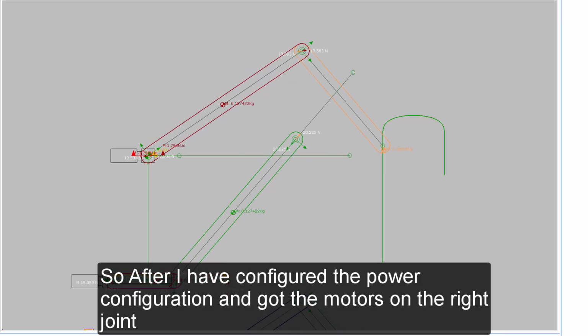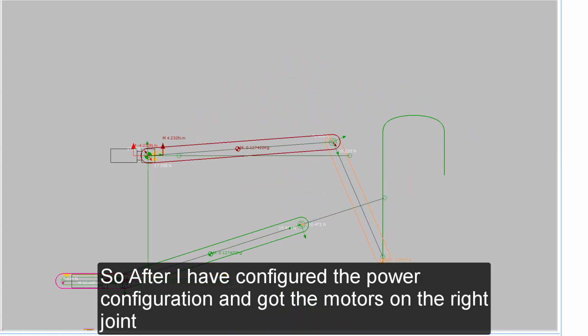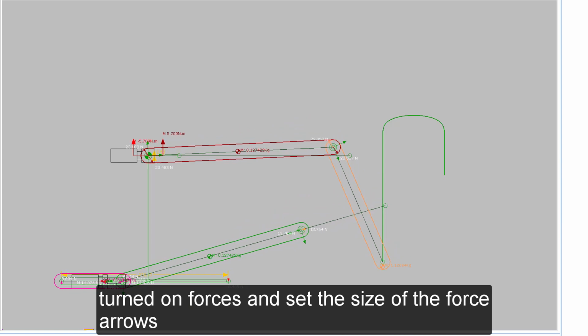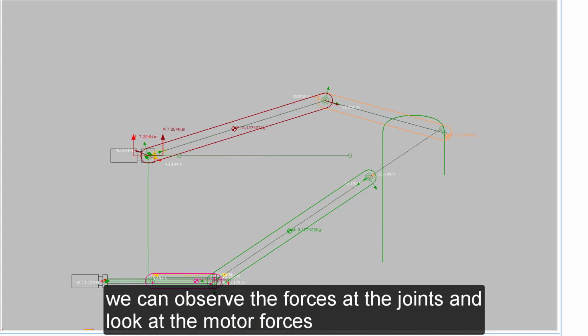So, after I have configured the power configuration and got the motors on the right joint, turned on forces and set the size of the force arrows, we can observe the forces at the joints and look at the motor forces and torques.